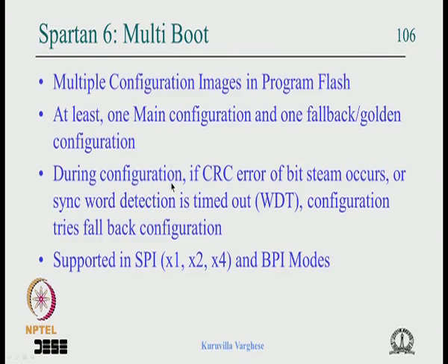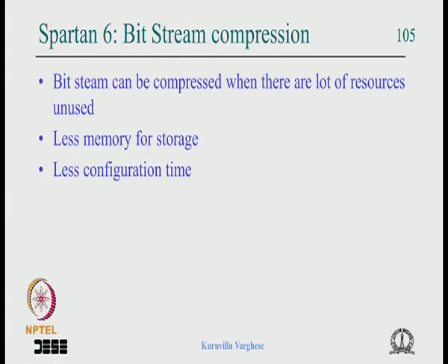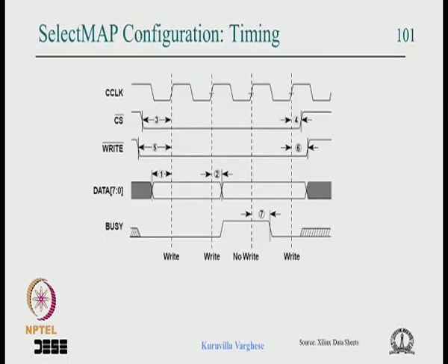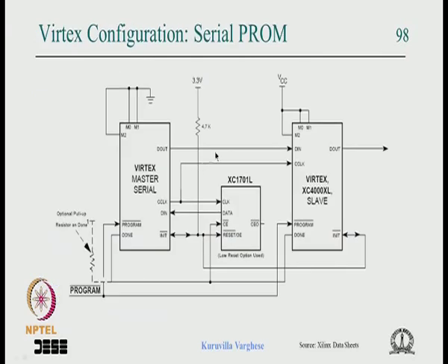Another possibility is that you have programmed a configuration in the field, like in flash memory, and sometimes the flash can get corrupted. Suppose the flash gets corrupted, then the whole device may not work, and the flash needs to be reprogrammed.